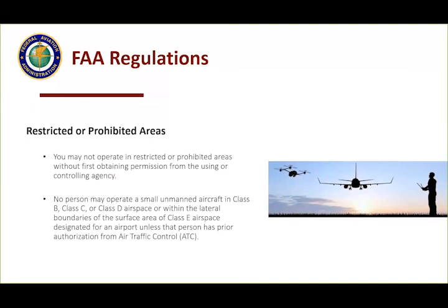I think your first guideline is if you're operating within the Part 107 regulations and you have your commercial license, you're going to be fine. You're going to be held to the 400-foot ceiling. You're going to be held to no flying at night, no flying over people, all the same regulations that restrict a general user. If, let's say, your department got FLIR and you're going to have to fly at night for suspect searches, you're going to have to get a waiver from the FAA to authorize you to do that. I hope that helps that question.